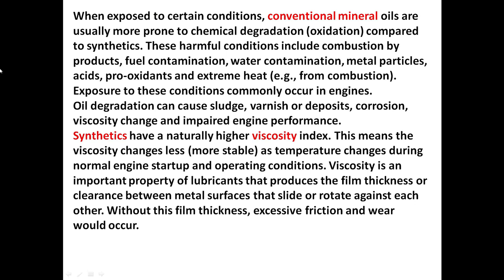When exposed to certain conditions, conventional mineral oils are usually more prone to chemical degradation, like oxidation, compared to synthetics. These harmful conditions include conversion by-products, fuel contamination, water contamination, metal particles, acids, and pro-oxidants like extreme heat, for example from combustion. Exposure to these conditions commonly occurs in engines. Oil degradation can cause sludge, varnish, or deposits, corrosion, viscosity change, and impaired engine performance.